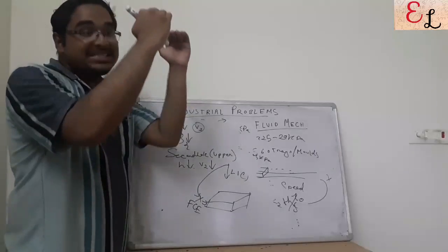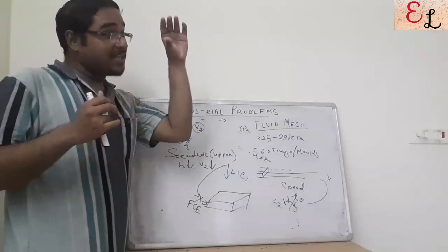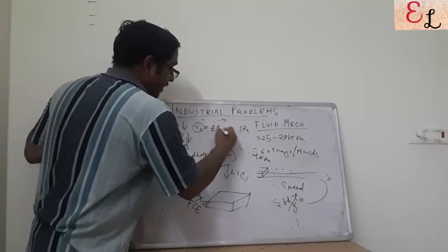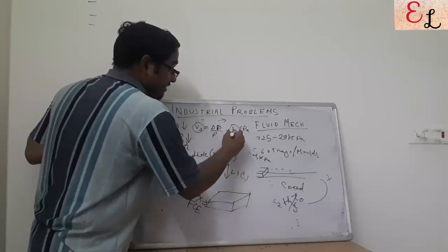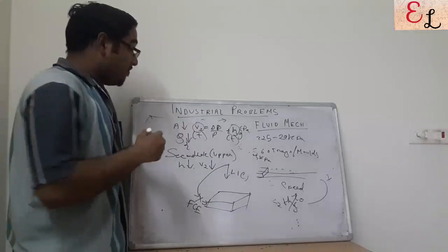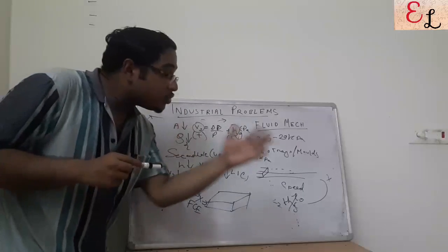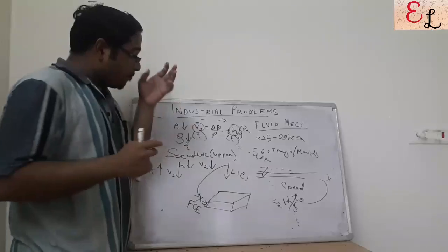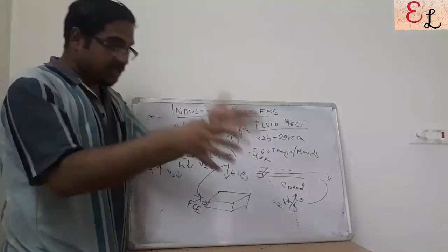Now, as the bed level keeps on decreasing, the exit speed also keeps on decreasing. Remember that, because the height of the slag bed is slowly decreasing. You see that the final equation of V2 was delta P by rho, something like this, plus Hg. So this H is a factor of time. So V2 also becomes a factor of time. With time, V2 decreases. The liquid flow rate becomes slower as the H keeps on decreasing over time. So thus, at the end, that problem will not occur, the overflow problem. The overflow problem will occur at the very beginning when the velocity is very high.